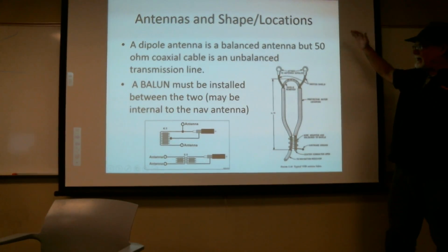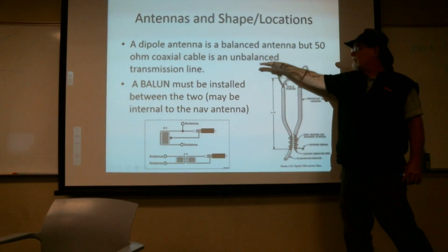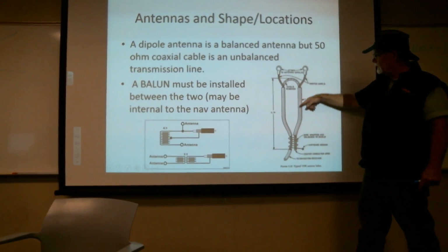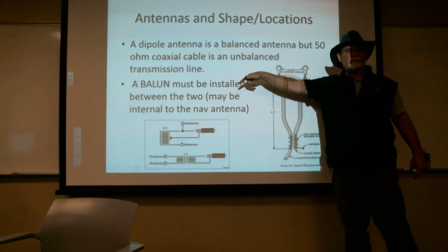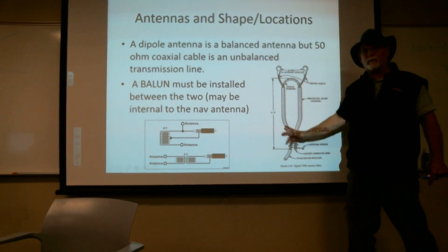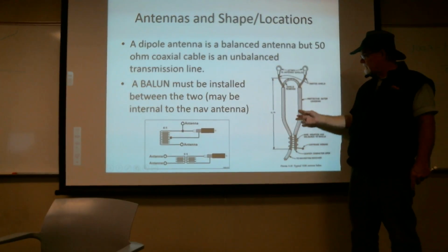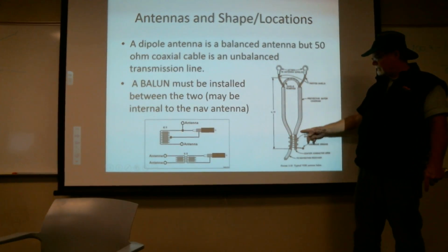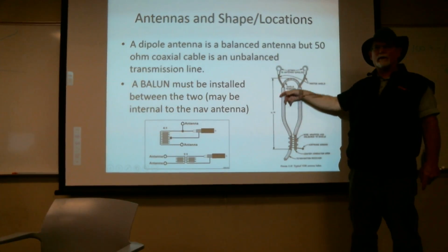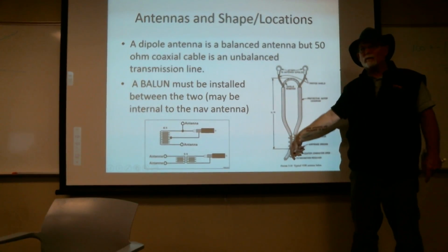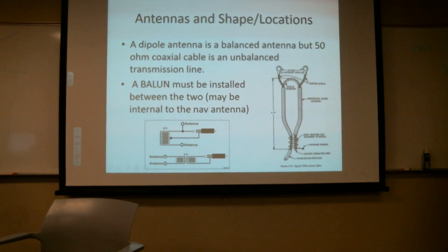Now what will happen is the electromagnetic radiation will hit both of these, and there'll be a voltage surge back and forth through the shield, which will then incite inductively a surge back and forth in the interior wire. Okay? Now the interior wire will get, and of course the length of this is going to be very, very critical, so that the wavelength of the signal isn't canceling the wavelength of the induced signal inside the center conductor. Okay? So that's one type of a balun.